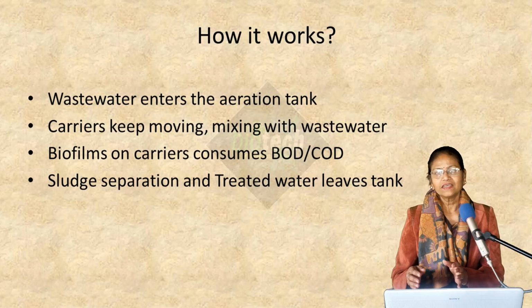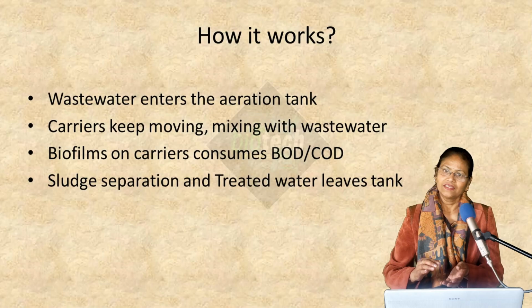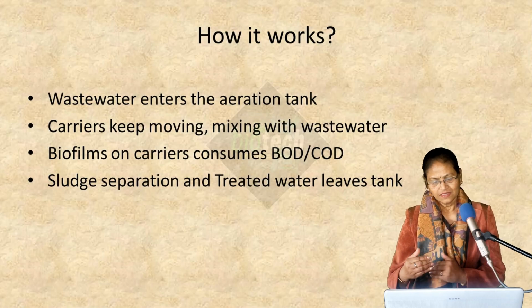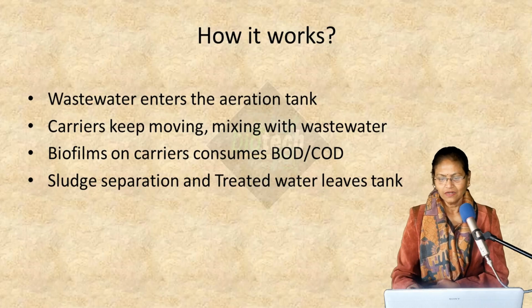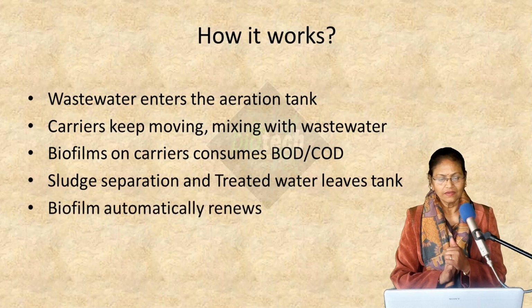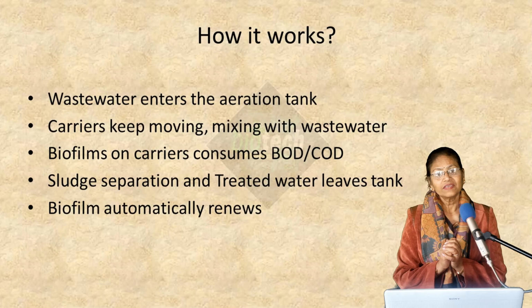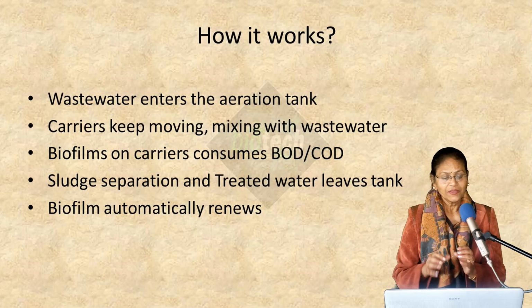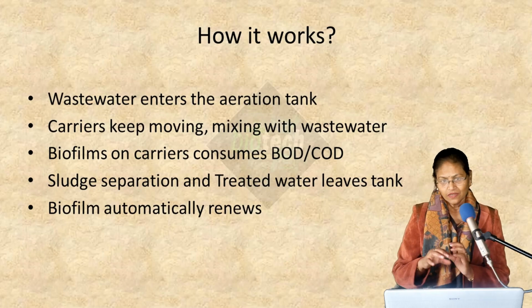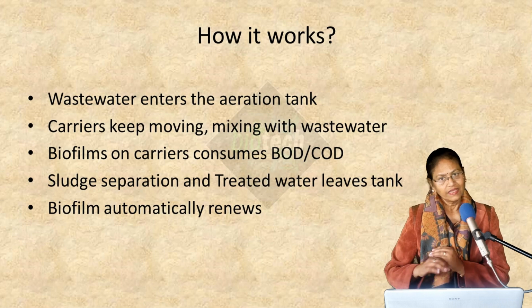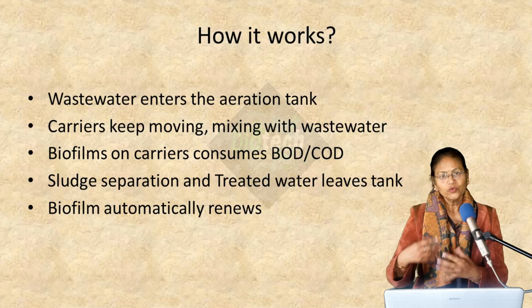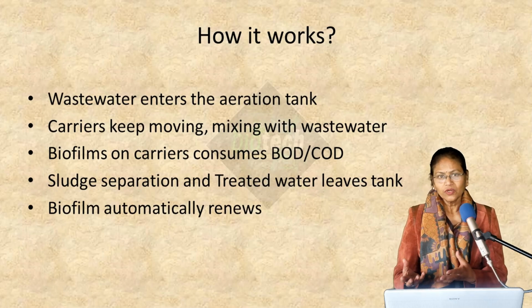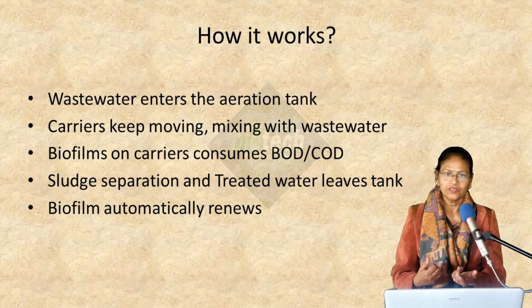in the secondary clarifier. So here the water will go to the secondary clarifier, and in that tank the sludge will be separated from the treated water. Treated water will leave the tank. And another very important point here is that biofilm automatically renews. The older microorganisms will shed off, and the new will be formed. So you don't need to do anything, automatically it will be renewed.